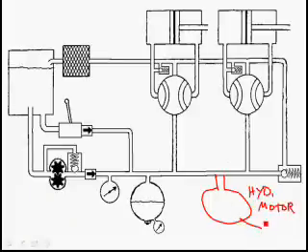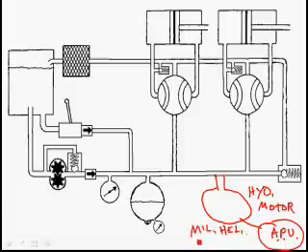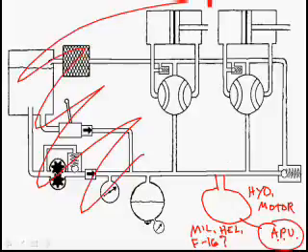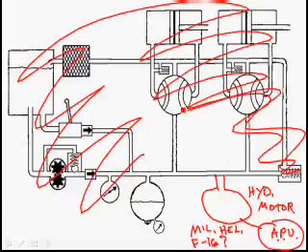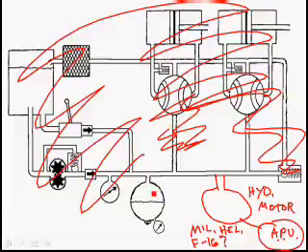And this hydraulic motor would start up an auxiliary power unit, a little tiny jet engine. You're going to find this in some big military helicopters. And you're also going to find this on an F-16. Anybody ever heard of an F-16? On an F-16, they don't hook this into the main hydraulic system. Same thing for these helicopters. They don't hook it into the main hydraulic system. But they have an accumulator.